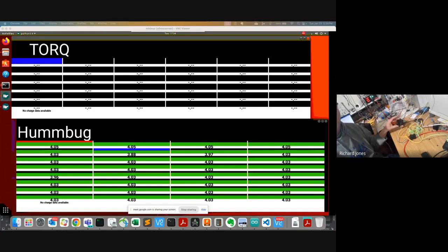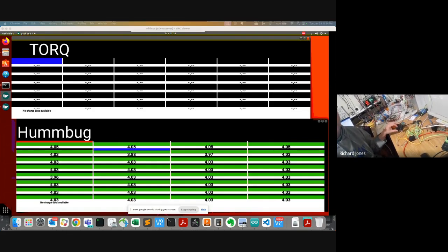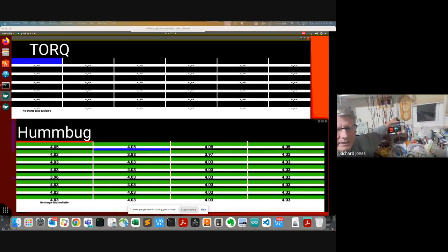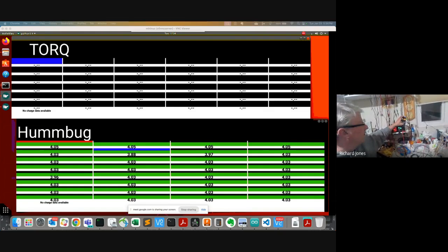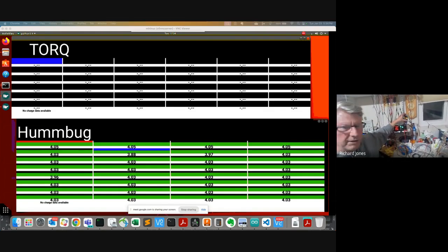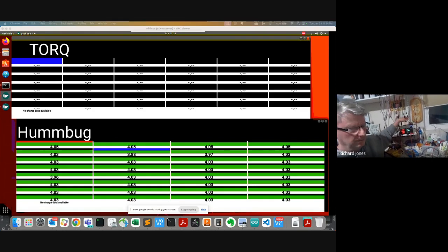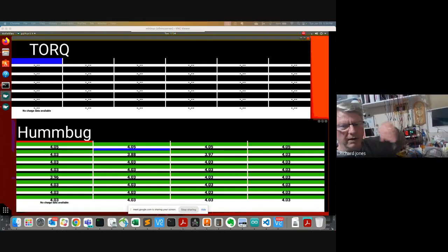Okay. I bought two of these together from China, and they worked out to be $80 each. But they're well worthwhile if you're putting it in a real product. And then this IVT up here is even more expensive, but it also has the high voltage sensors, three on there, so you can watch the voltage before and after your pre-charge, for instance. These are expensive, but these are commercial vehicle quality products.